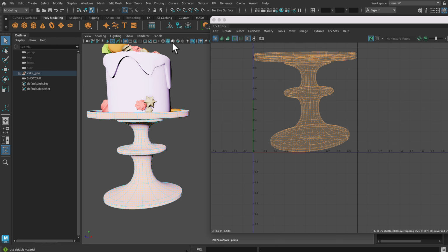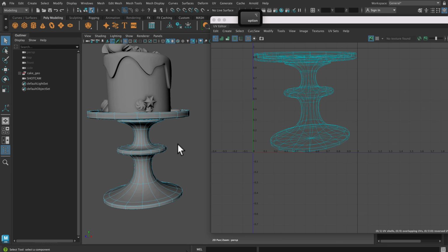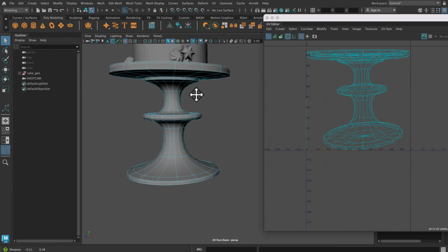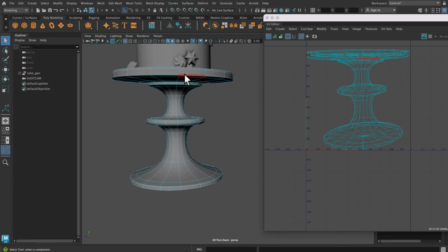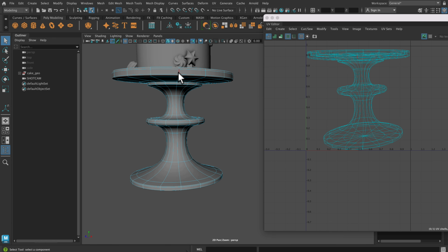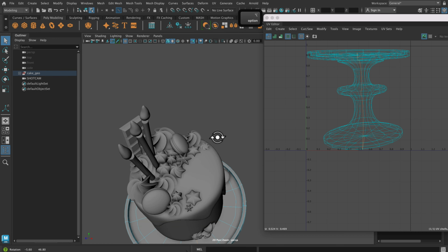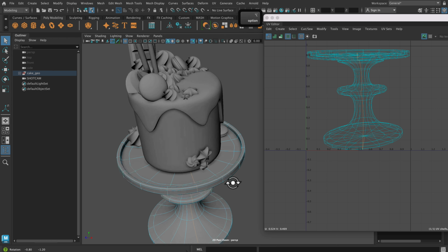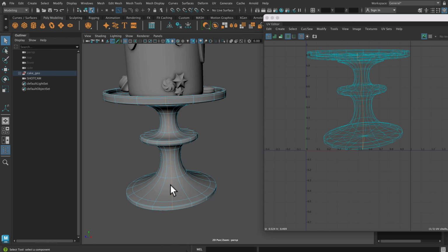So this one, use default material, so you can see a little better. And what I need to do is select some edges that will be cuts. So I'm going to right click, select by edge, find one of these vertical lines and double click it. And that's going to be one of the cuts that I make for these vertical pieces.